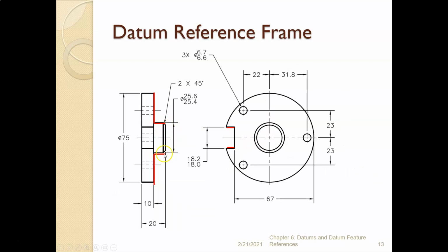So the cylinder is also an important feature when we ask ourselves, where does the part live? The surface goes onto the surface of the body, the cylinder goes into the hole in the body, and finally, the key goes into this groove or notch in the cover. And I've identified all these surfaces as red. So that's the unique location where the part lives.